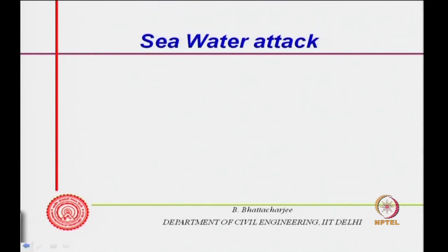So, this is sulphate attack. Using sulphate resisting cement, blended cement, and low water cement ratio are usually the strategies against sulphate attack. You can see it, it is there, but in the Indian scenario it is less common than, let us say, reinforcement corrosion. Reinforcement corrosion is one of the major problems.